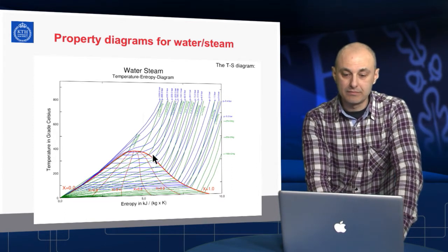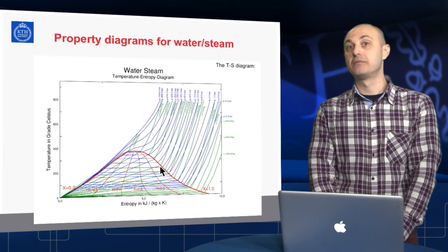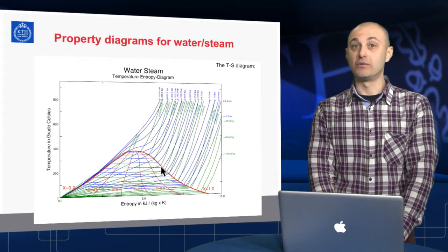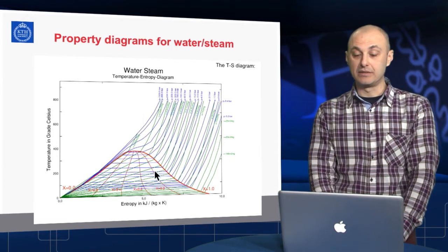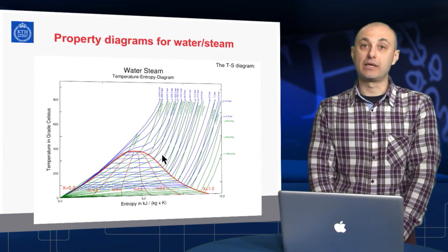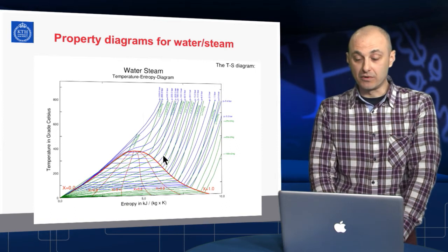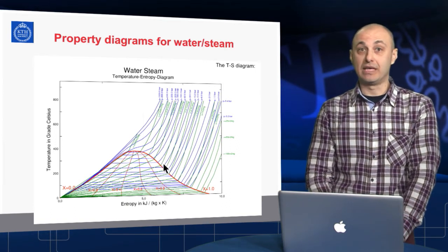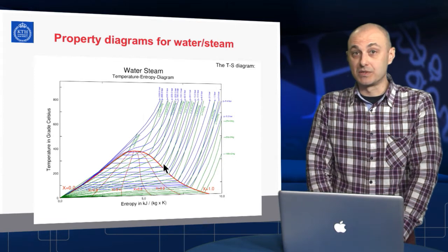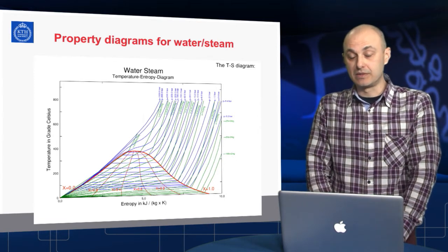Remember that we see steam only if it's more or less saturated or if it is inside this wet zone. Superheated steam is not visible. It's rather like air, completely transparent. What we see in terms of fog or steam coming out of a kettle, that would actually be the water droplets, the small condensing droplets inside the steam flow.